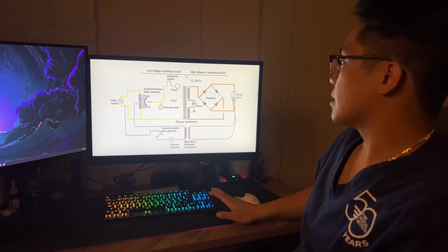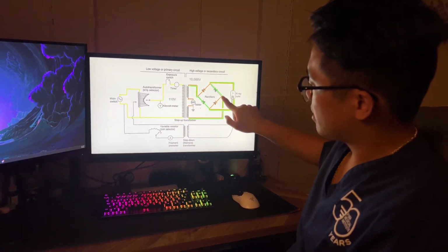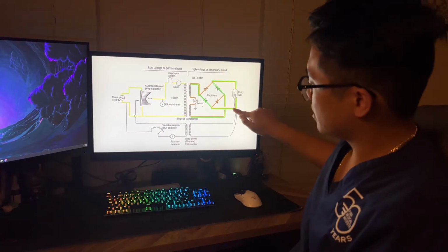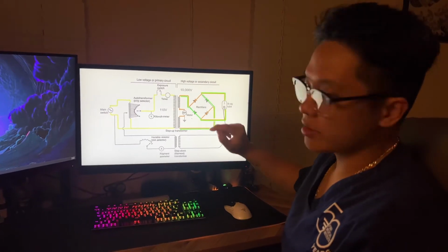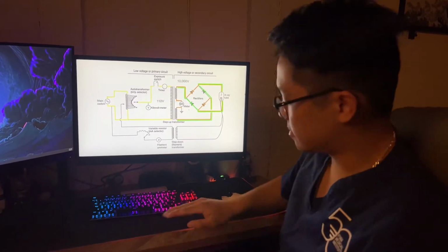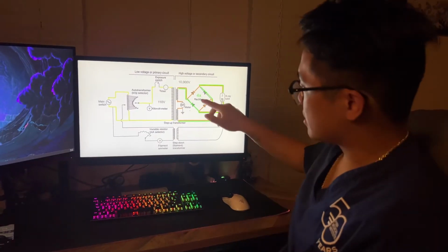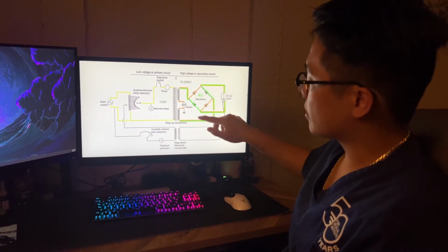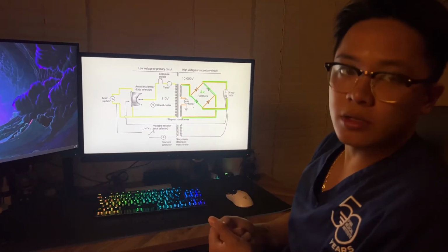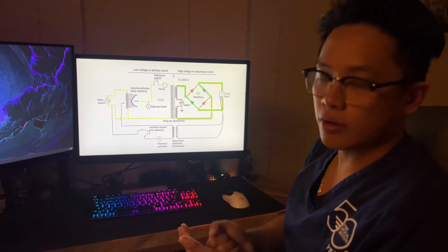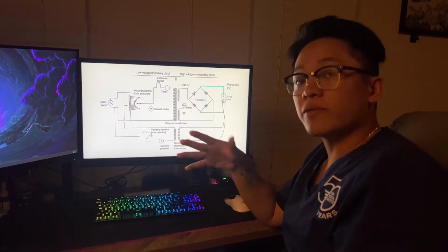The secondary one is going to be this one. It goes from the bottom up, makes that little turn up here, and goes to the coil. This is one of the pathways where it happens 4 times. Yep, 4 times right there. So the rectifiers are making sure, with the diodes, that everything's flowing in one direction, and rectifiers will change it from an alternating current to a pulsating direct current. And the pulsating direct current is the most efficient for X-ray.